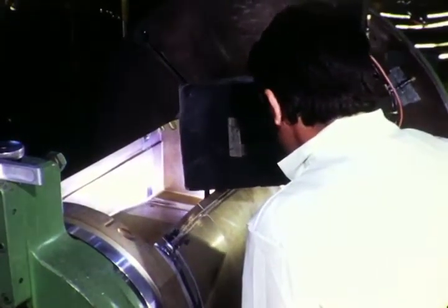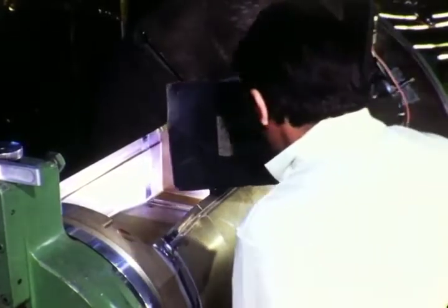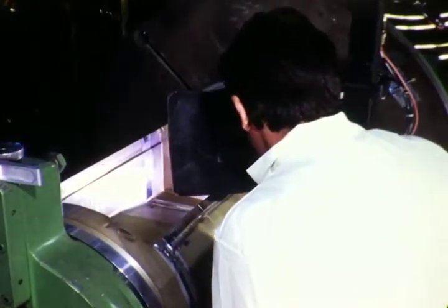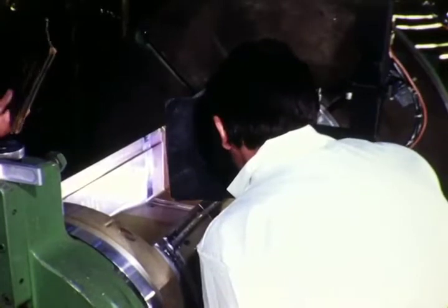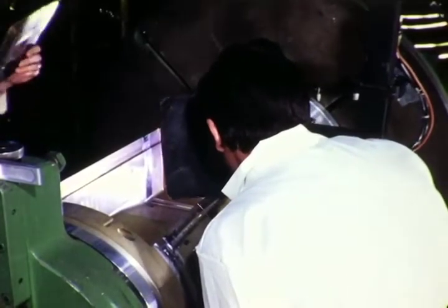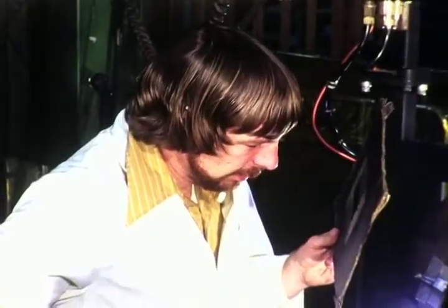The thickness of the square butt weld joint in the cavity area is just under a 1/4 inch. The material is alloy 2219 aluminum, welded in the aged condition, then re-aged after welding.